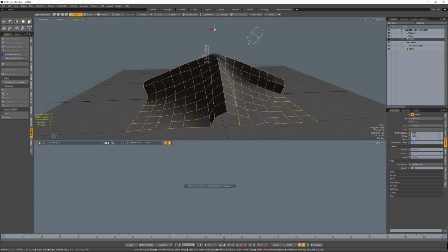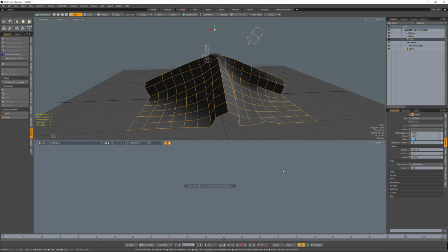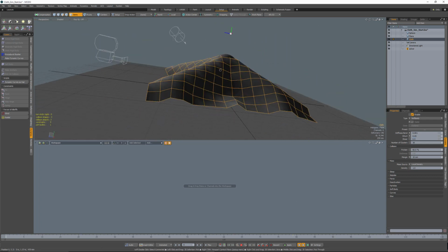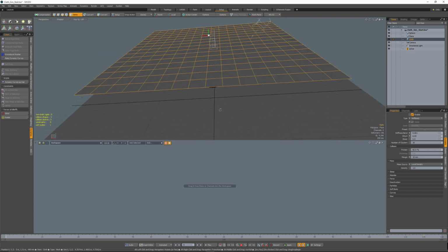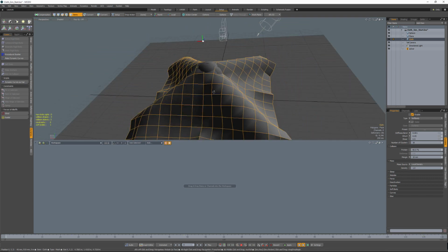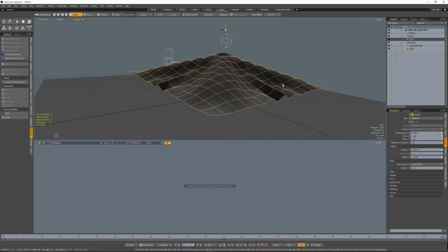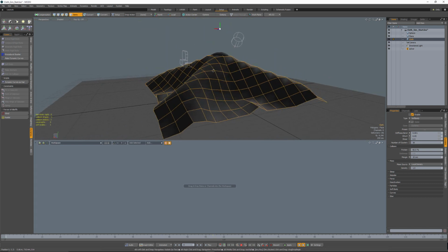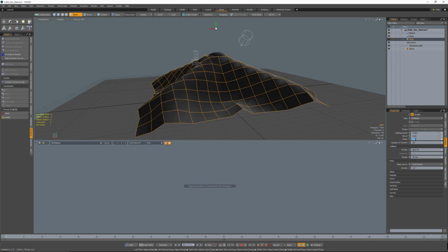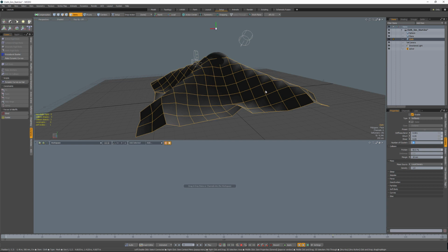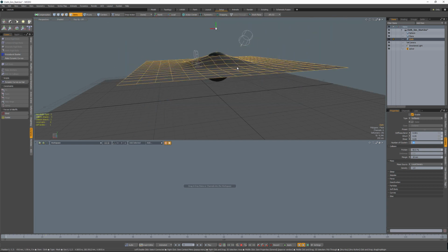The minimum is 0.05 actually on both of these. So let's put this down to 0.05, and we'll let this loop around again. And you'll see that all of a sudden we no longer get those straight lines where we have these edges. Those start to collapse, but we still see straight lines diagonally, and that's because our shear is still set to 0.5. So if we take the shear now and we put it down to 0.05, it's not going to make a big difference until we actually run through the sim again, but there you go.